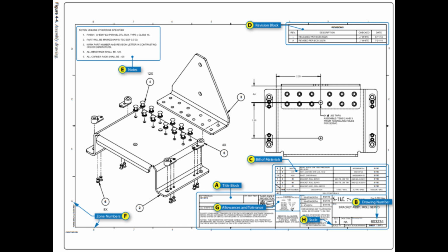Finish marks. Finish marks are used to indicate the surface that must be machine finished. Such finished surfaces have a better appearance and allow a closer fit with adjoining parts. During the finishing process, the required limits and tolerances must be observed. Do not confuse machined finishes with those of paint, enamel, chromium plating, and similar coatings.